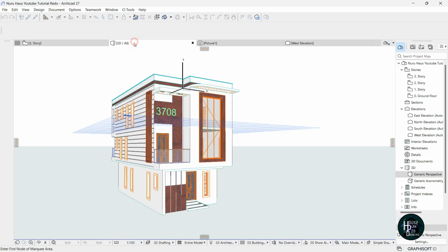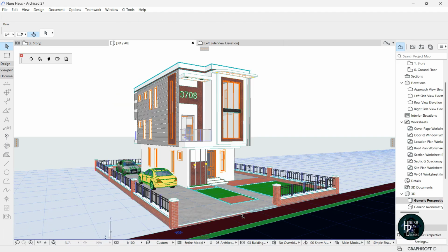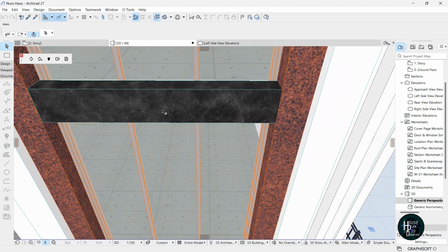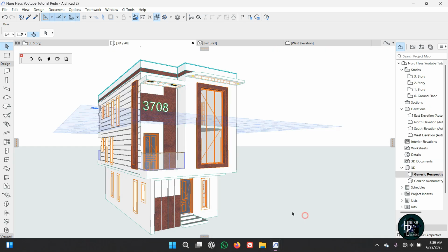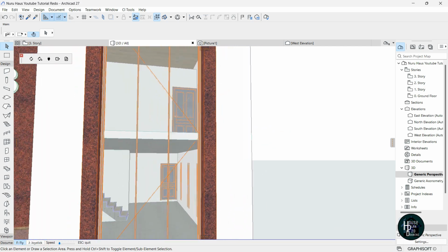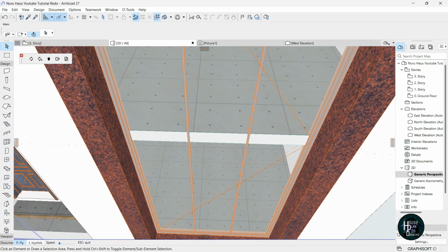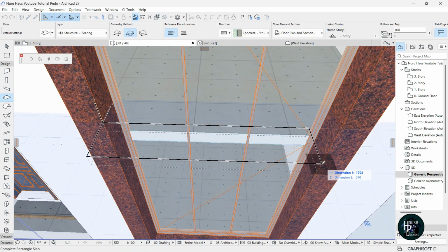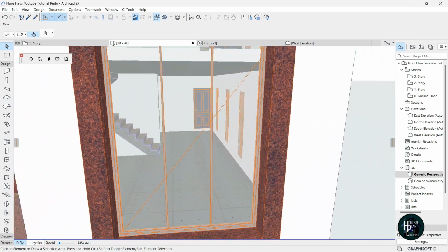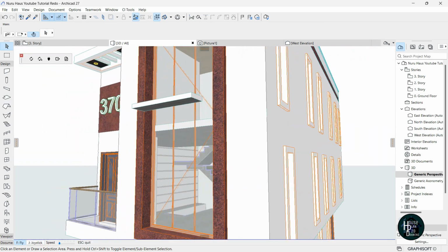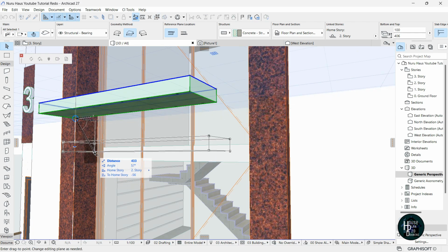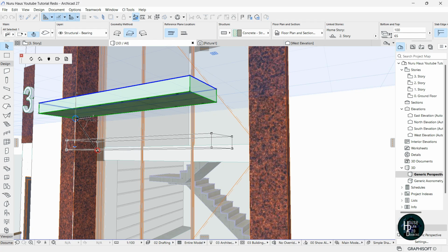Now if you go to your 3D view, if you look at this one I had here, if you come to this side, you're going to see something like this. This is also a slab that I used to design this. So if you want to also do this, you can just come to this side here and move in closer here. Come to the slab tool, click a point here and click another point here, then click. Once you do that, zoom out, click the slab, press Ctrl D on your keyboard, click this and try to move it to merge around that side there. Just click.